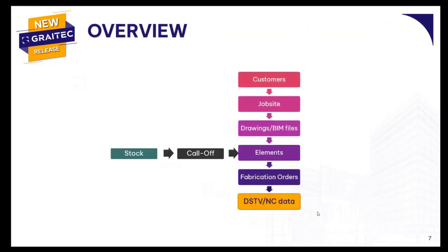So once again, here to manage the elements, of course, you would need to verify if you have the raw material in stock to produce the assemblies. If not, then we have a nesting module where then you'd be able to verify how many bars are required for the entirety of the fabrication order, or plates for the entirety of the fabrication order, and then procure the material. In the latest release in 2025, you can actually manage this on multiple fabrication orders at the same time, meaning you can nest each individual fabrication order, but then after group them all together for one single purchase.